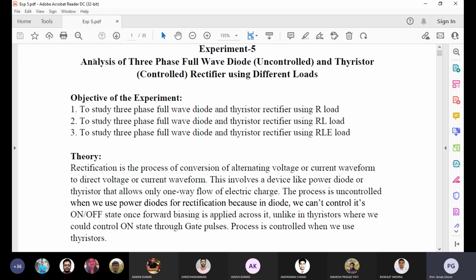When rectifying from AC to DC in single phase, the main problem is that we are only changing the pulses. If it is a 50 hertz AC signal, then when it becomes pulsating DC you get 100 hertz, so the DC has two pulses.